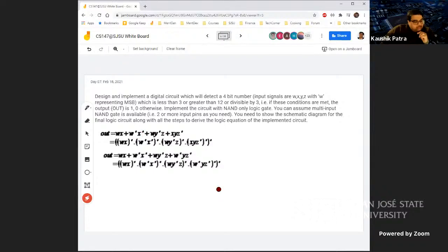used De Morgan to convert into NAND. The whole thing is something or something or something or something. That means with De Morgan, it becomes those terms inverted and ANDed, and the whole thing is inverted. So the entire outer logic is a big NAND, and then individually I went through the corresponding conversion, converting them into NAND, so that becomes the solution.